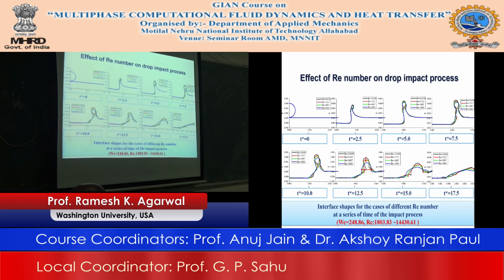There is a physical interpretation of the way the Reynolds number is affecting this. Reynolds number has no surface tension in it, while the Weber number has a surface tension in it. So it turns out that surface tension forces are taking a much bigger role. What is a Weber number? Weber number is the inertia forces divided by the surface tension.